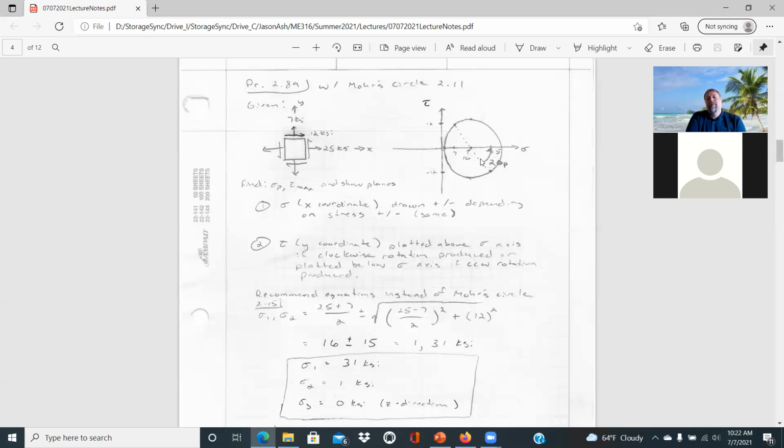The other thing to just be aware of from your Mohr circle world is that the angles are multiplied by 2. And so the angle here would be 2 times the principal plane orientation. So you'd have to divide that by 2, this angle here in the Mohr circle land, to figure out that actual rotation.